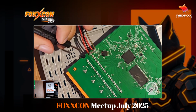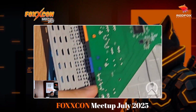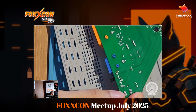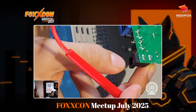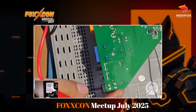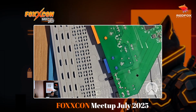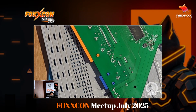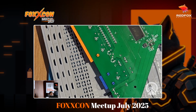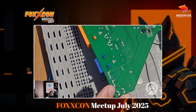Okay, so for that, we're just looking for a beep. So this right here is the power pin for the router. You connect the power here. So one of these is your ground. Just try randomly which one it is for now, because if we try out all 4 pins and nothing beeps, we know the one that we are testing is not really the ground one, because it would have beeped otherwise.